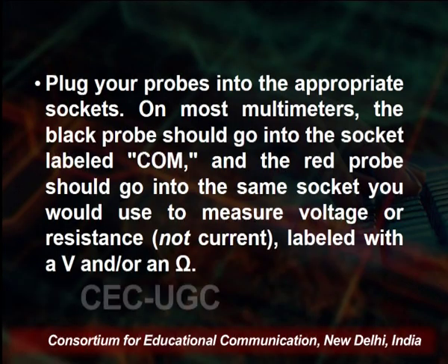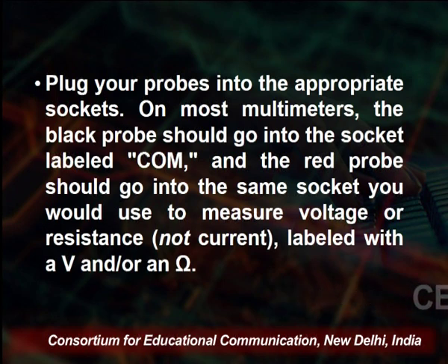Now the symbol might not look the same on all multimeters, but it is mentioned as continuity check, and most multimeters have the continuity check. Then plug the probes into the appropriate sockets.